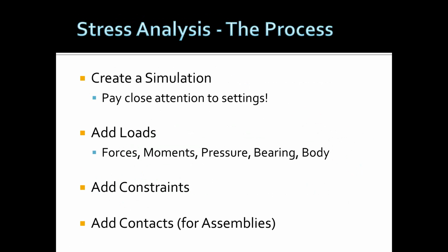If you have two plates that are typically bolted together, I just mentioned that you want to turn off the bolts. You want to suppress the bolts to make the simulation run faster. You can put a contact, or contact joint, if you want to call it that, between those two plates, and it simulates that bolted connection. In a sense, you're calling it a no separation contact, almost like a welded or glued contact.